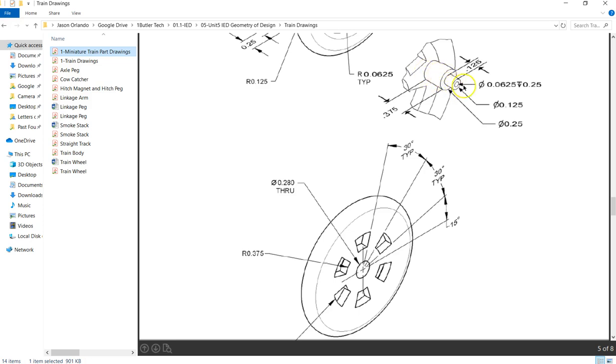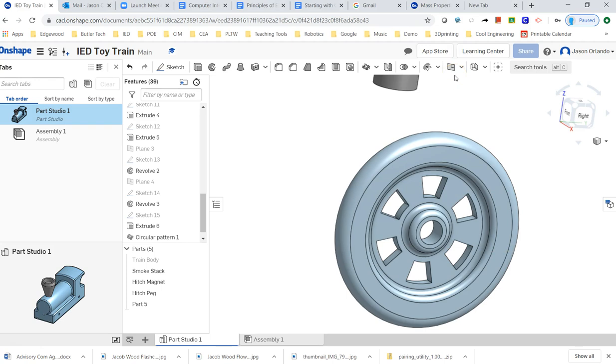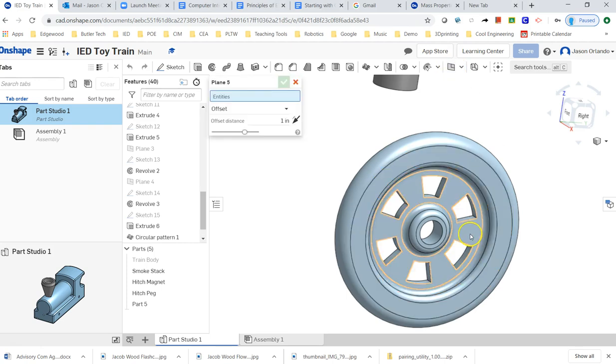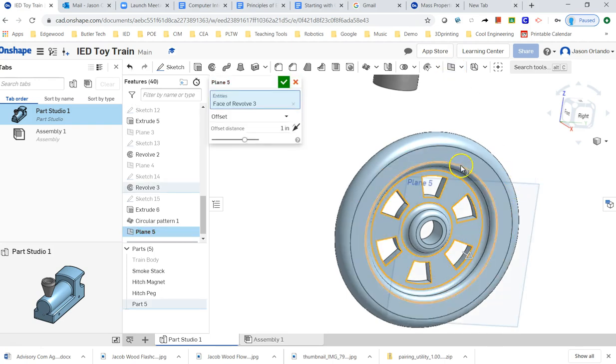And that whole depth does not match this extrusion, so don't just do a cylinder and extrude that out. If you pay attention to the depth here of that hole, that is deeper. That hole is going to run into that bottom cylinder, and so we'll do a small cylinder, and then make the hole. Okay, get that? So I'm going to create a work plane. It'll be an offset plane from here, and it's going to be a distance of 0.375.